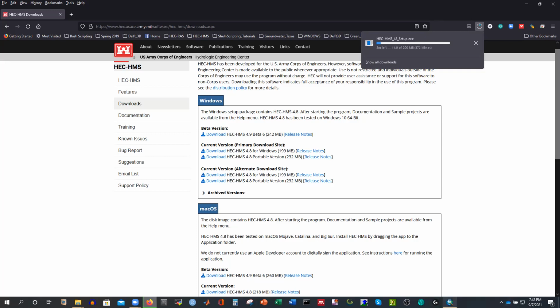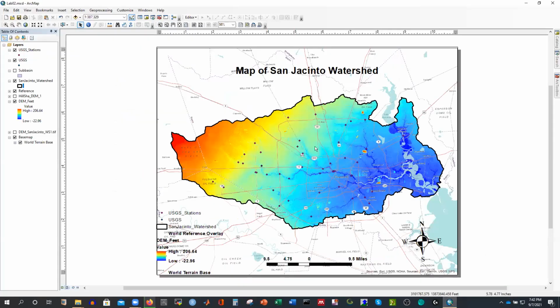So I'm going to explain in the meantime. Since I already have this DEM for this area, I will use it, and I already converted this DEM from WGS units to state plane. So my horizontal unit is in feet, and I already converted the vertical unit as well. Previously the vertical unit was meters, and by this time I converted that to feet. So whether it is vertical or horizontal, both are in feet.